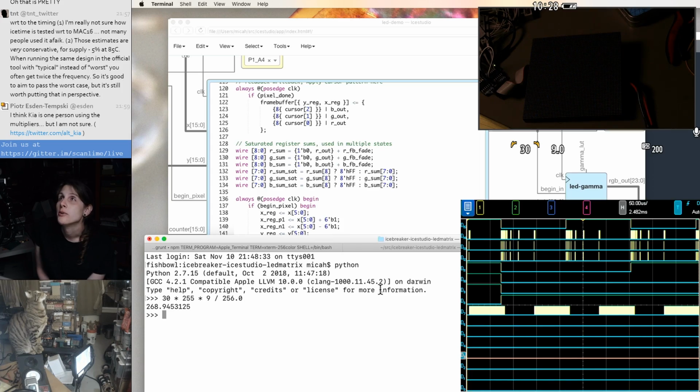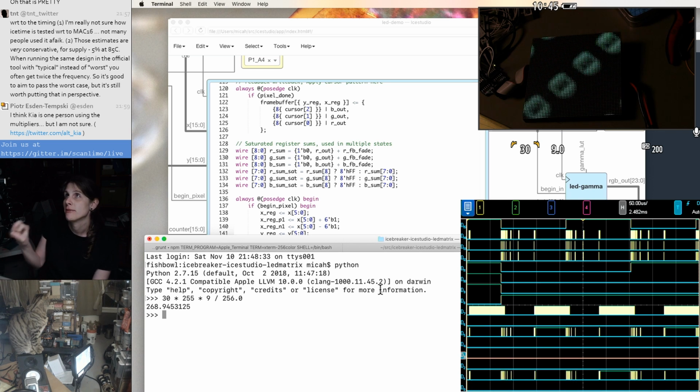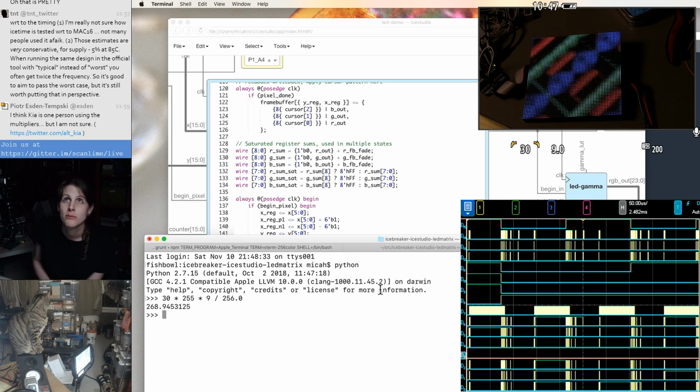So you're seeing that attenuation and blurring, and then the pattern that we're writing into the buffer before doing that blurring, or in addition to that blurring, is this kind of munching squares. And the timer for the munching squares pattern is different for the red, green, and blue channels. I've shifted those over by 1 bit, so that's why you see the different munching squares kind of overlapping a little bit.